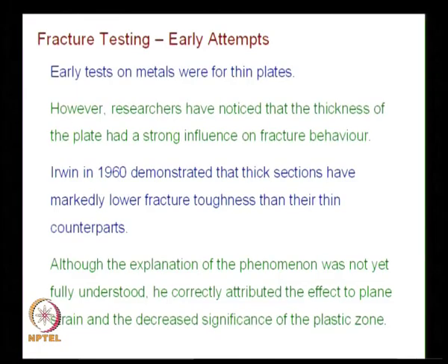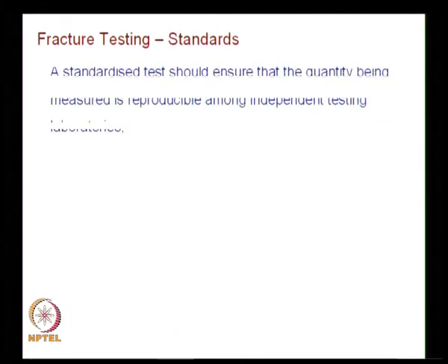In the case of plane stress, now you know the size of the plastic zone is much larger than in plane strain. So, the experiments reveal the fracture toughness in the case of plane strain is far below what you have in plane stress. An intuitive understanding was provided by Irwin. Later on his result was corroborated by further experiments and discussions.